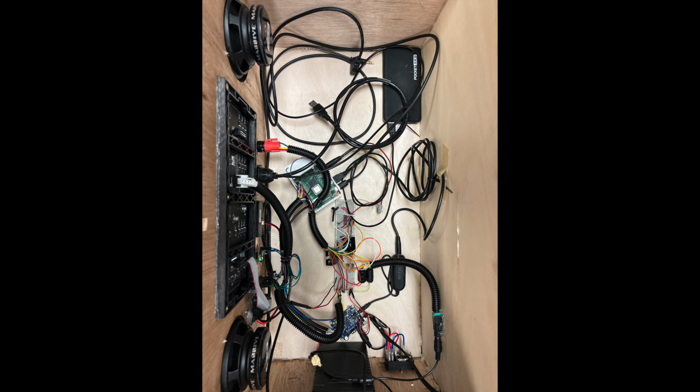Lastly, we have an analog to digital converter externally connected to the Raspberry Pi. The power to this analog to digital converter is connected to the 3.3 volt output on the Raspberry Pi so that the analog to digital converter turns on and off when the Raspberry Pi is turned on and off to keep our signal continuous.